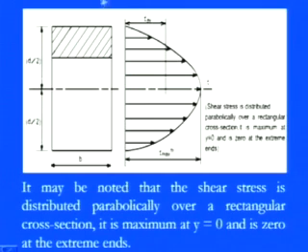So now just keep those things in your mind. We would like to describe those things in a graphical way. We are focusing on the same rectangular structure which we used in the previous section. This is a rectangular cross section, and we have this particular strip, which is our matter of concern. D by 2 is the height, so the total height is d. At this neutral axis, as I told you, the maximum shear stresses occur, so the value of that is 3 by 2 F divided by bd.